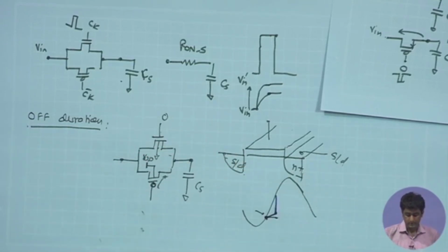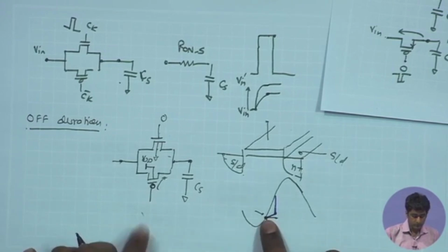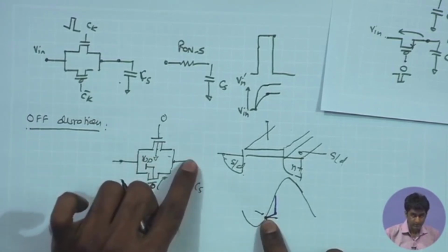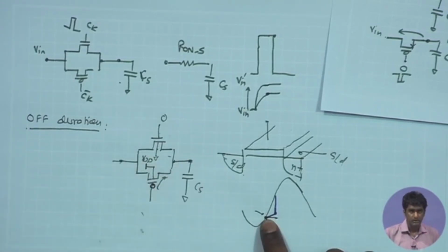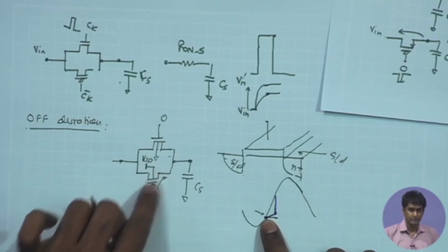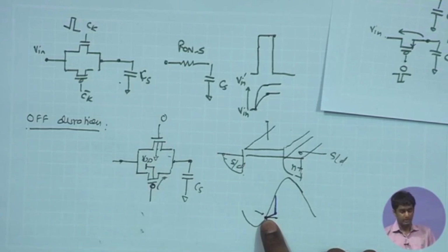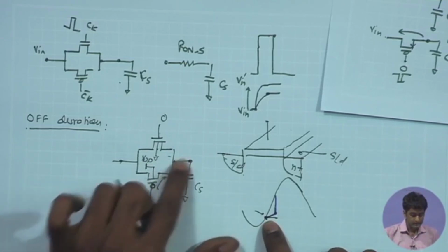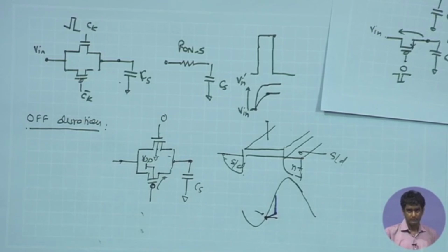again depending upon the condition of the switches over here it can show increase or decrease. So, when the input signal is low or the sample value over here is pretty small, close to ground, then the reverse bias junction leakage of the PMOS is going to dominate, and it is going to increase the sample voltage a little bit.